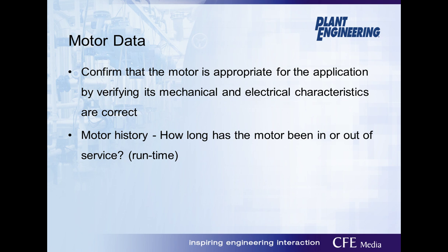This meaning, was the motor a spare that had been sitting on a shelf for a period of time before it was installed, or does the system have multiple motors that are used for the same process? There are many cases where motors will sit for months on end where there's no controlled environment and the motor shaft is never rotated. This can lead to many premature failures, such as flat spots on bearings or moisture buildup on the windings. Therefore, this makes this an important part of the troubleshooting process.